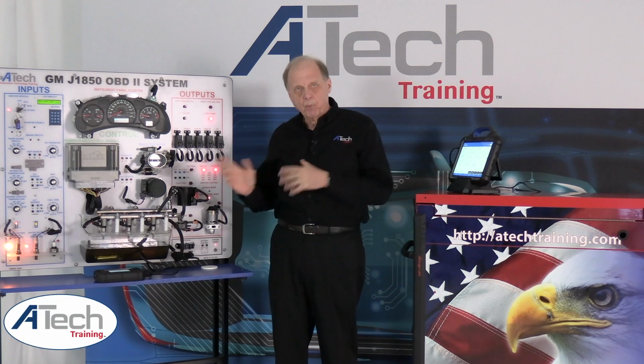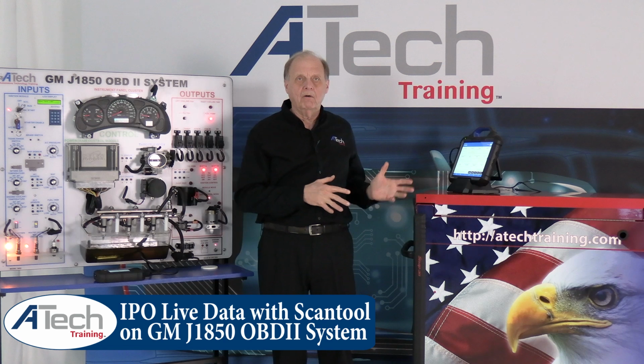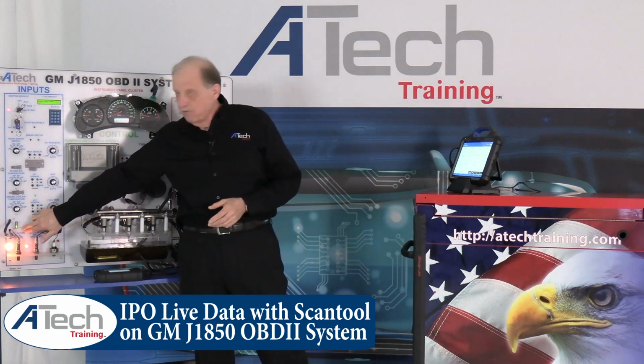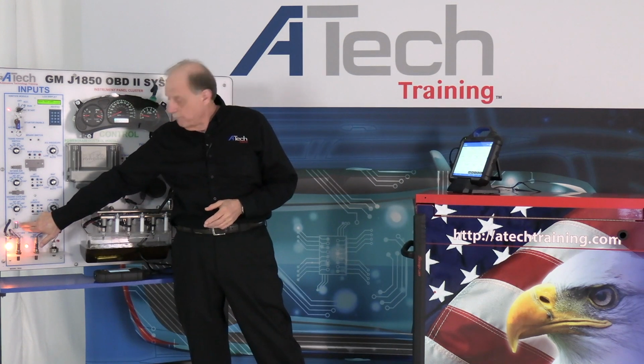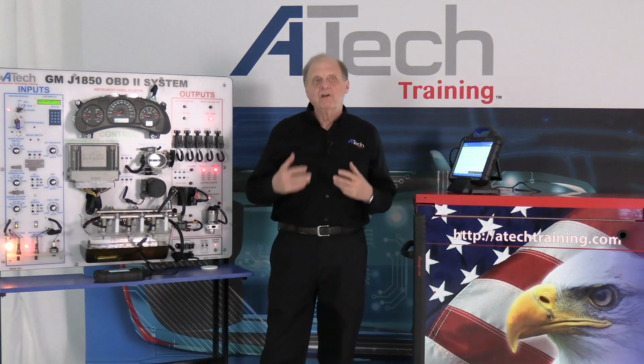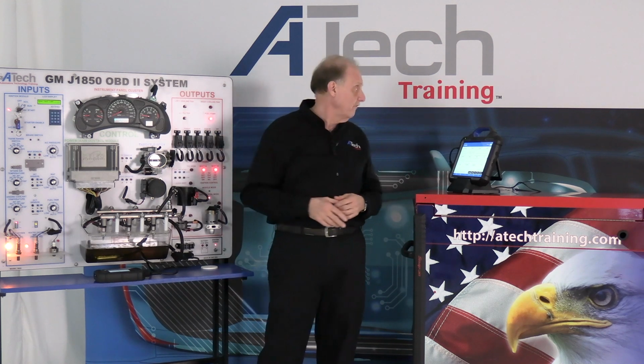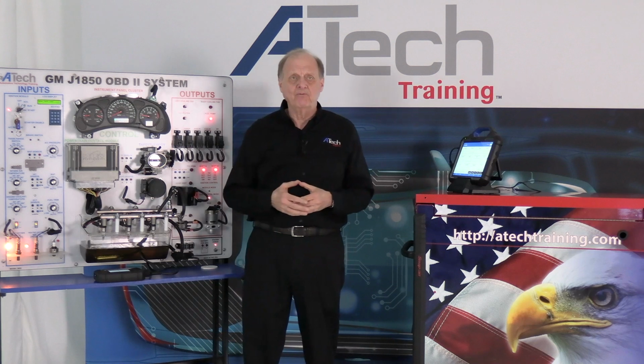Okay, we're going to look at the board for a second. We're going to look at the car, or the Scantool information. What I want to look at, first of all, is if you see the O2 sensors moving up and down with the bar graph up here. That tells you it's got activity, but it doesn't really tell you how high it goes and the average of it. Some of these Scantools will actually average the O2 sensor.